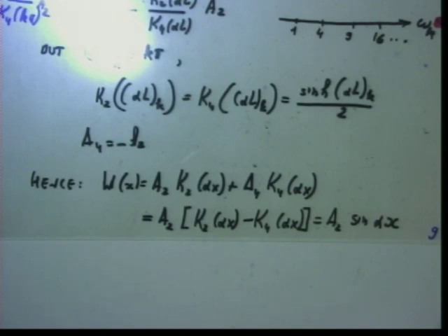And now we have this function. So that means that there is a shape. That is why it is called mode shape. It is not called mode function, but it gives us only a shape. The shape is a sinusoidal shape. But how large this value will be depends upon initial conditions, or the initial kick we impart on the system.